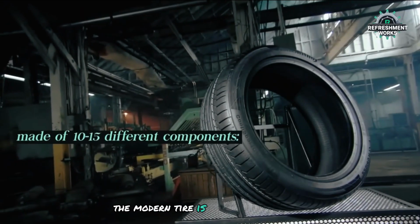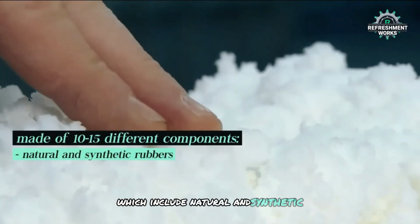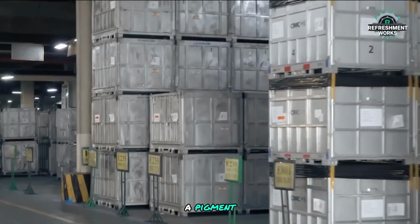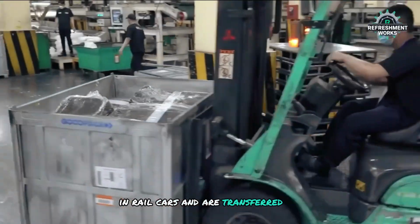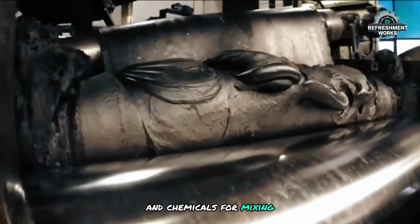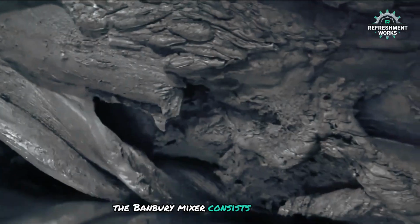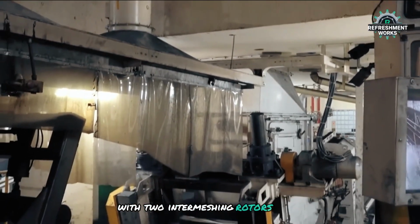The modern tire is made up of 10 to 15 different components, which include natural and synthetic rubbers, chemical additives, and carbon black, a pigment. These materials are delivered to the factories in rail cars and are transferred to storage. Then computer systems measure out specific batches of rubber and chemicals for mixing, which are then sent into a Banbury mixer. The Banbury mixer consists of a large, cylindrical mixing chamber with two intermeshing rotors inside.